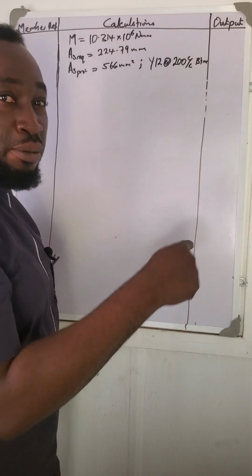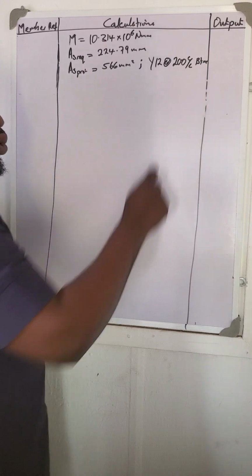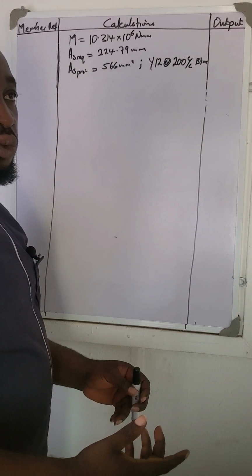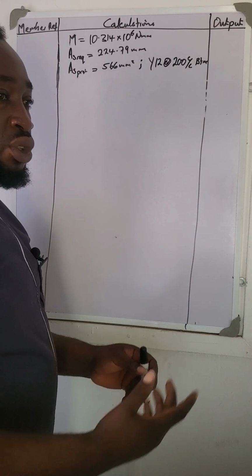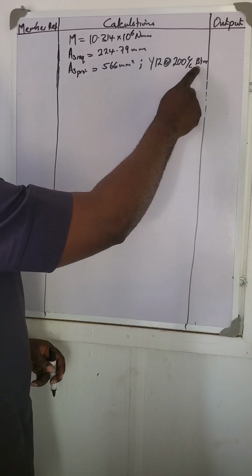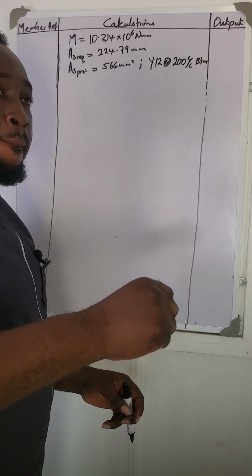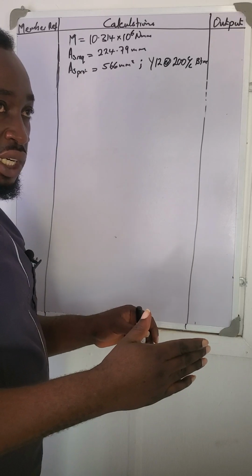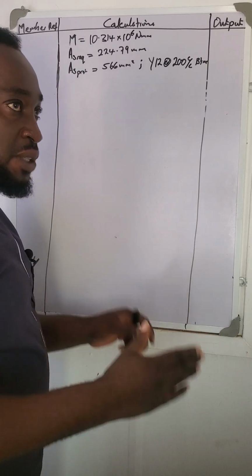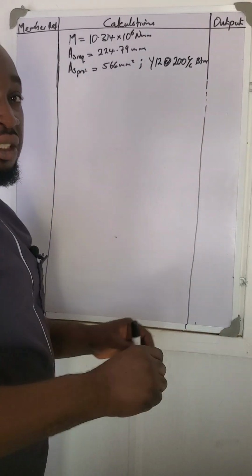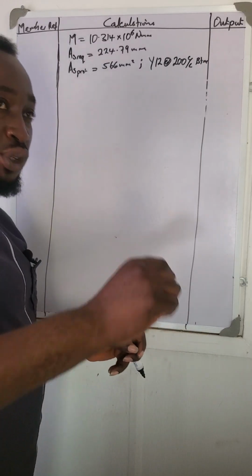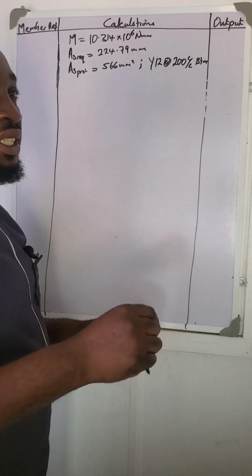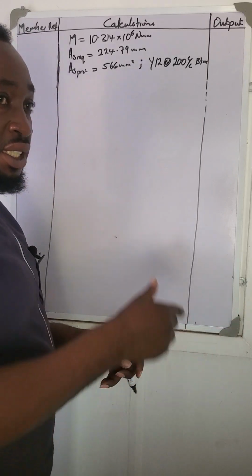Instead, you call it near bottom. When you come across a design and you see bottom, it means that it's the shortest span. The shortest span reinforcement is always at the bottom. Why the near bottom? That is for the long span, the distribution.